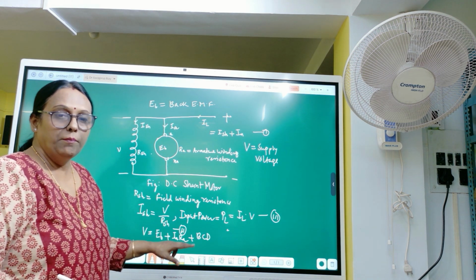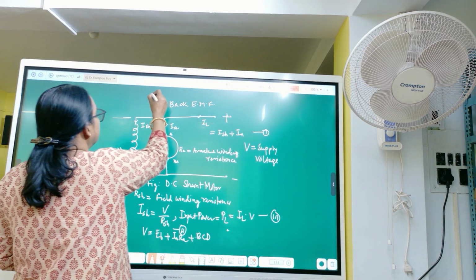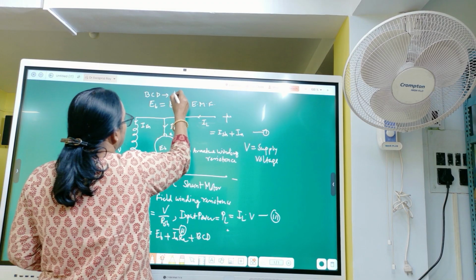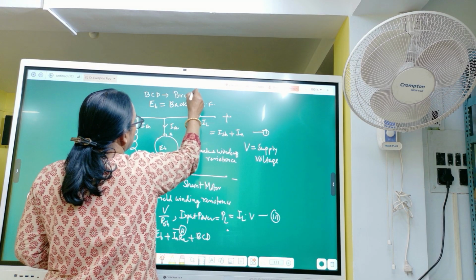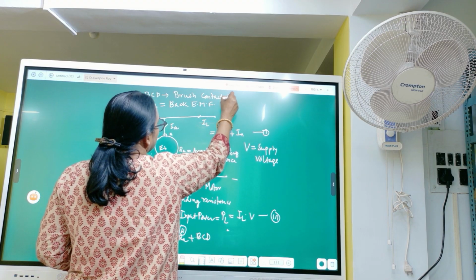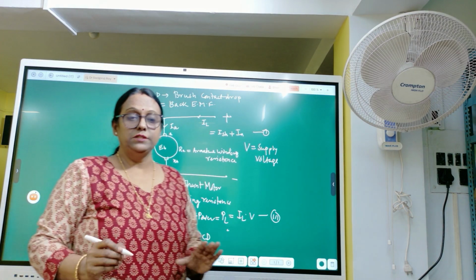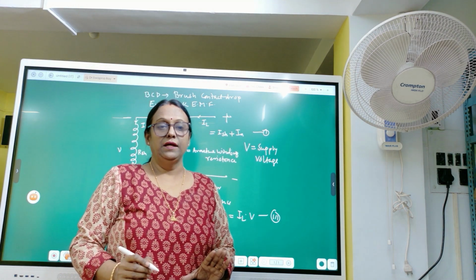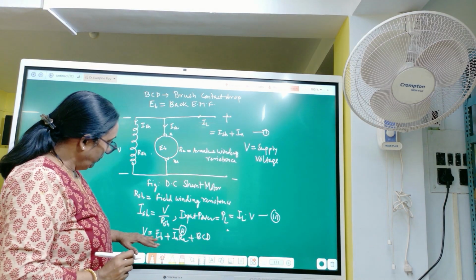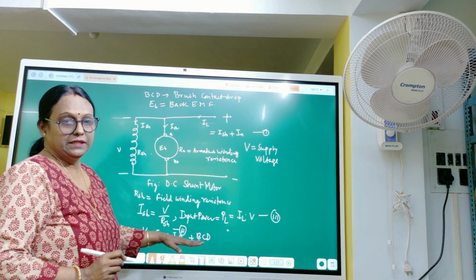BCD stands for brush contact drop. If it is not mentioned in the numericals, that means you have to consider it as 0. So terminal voltage is equal to back EMF plus IARA plus BCD.